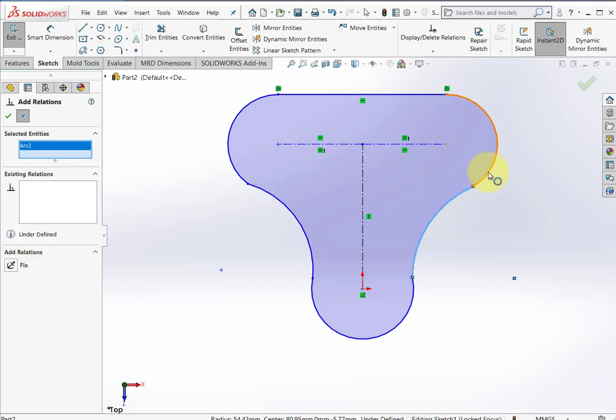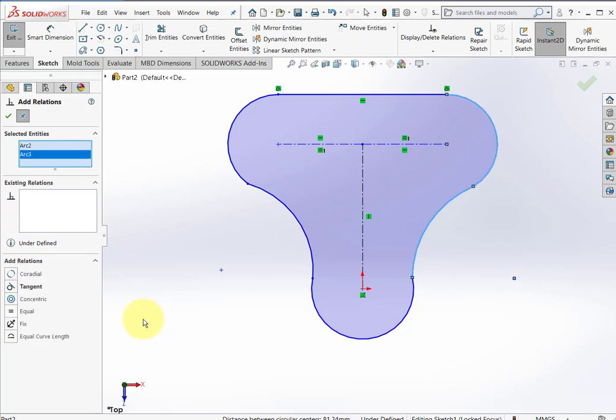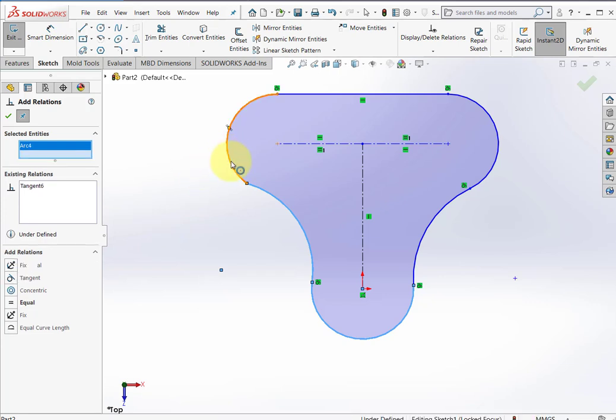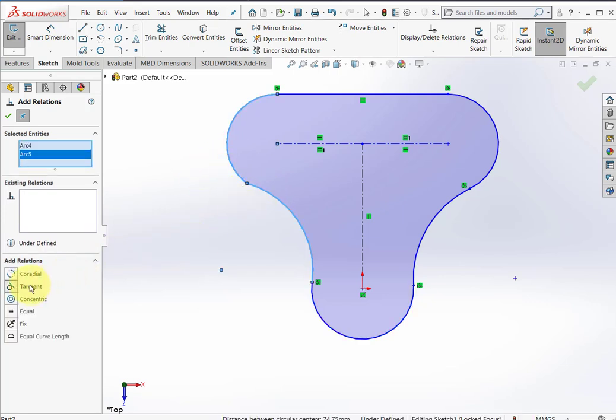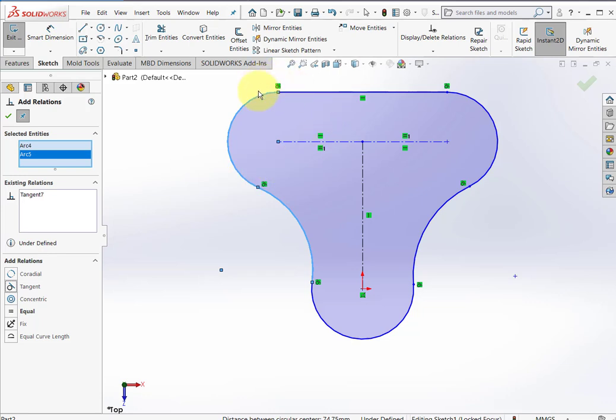And that's what I'm going to do for all entities in my sketch. I set them tangent. This one should be tangent. Also here. And here it's still tangent. Okay, what can we do more? These 3 arcs and this one should be equal.